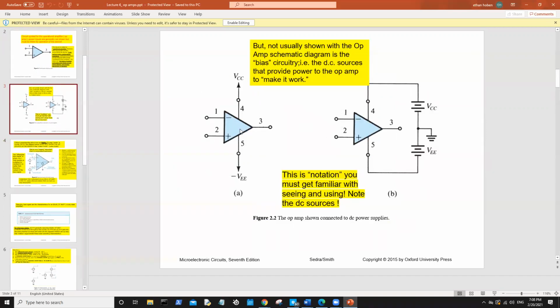It's good to remember that power rails are a thing, though we rarely consider them in our analysis of the op amp, since we're operating almost exclusively in the ideal range-ish, not really, since we sometimes have resistance values. But we just consider that there is no upper limit to the current gain or the voltage gain. Therefore, theoretically, we have infinite rail power. But that's not how it works in real life, so we have to consider that.